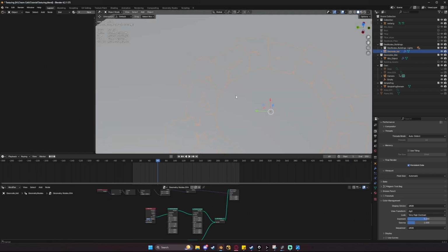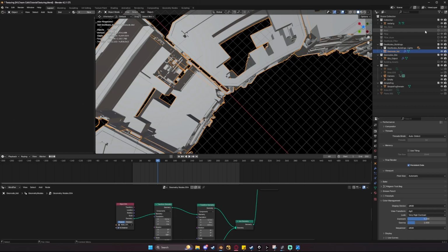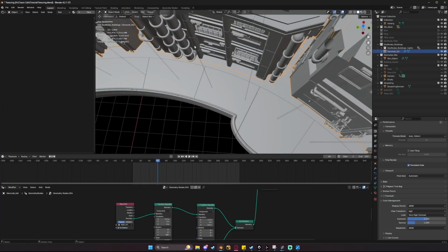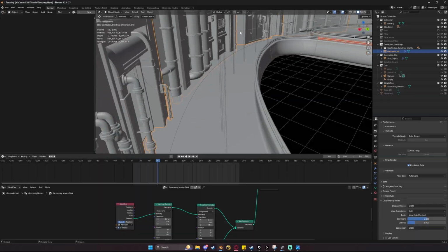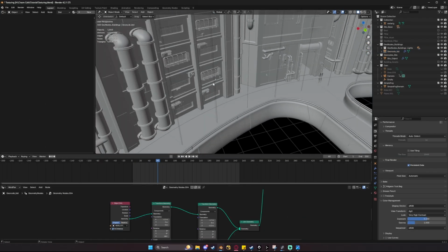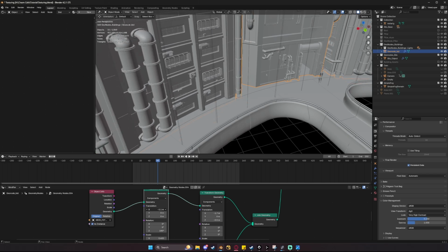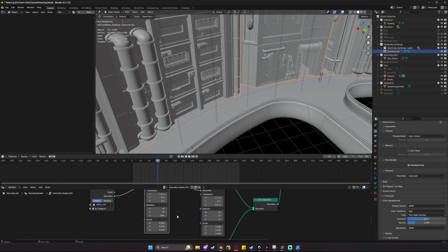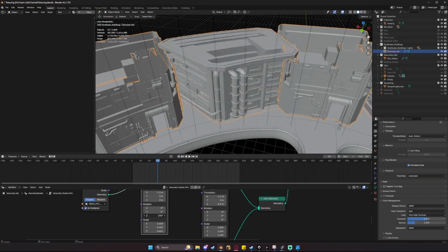One of the things I did was I just repositioned some of these buildings to line up a little bit more accurately here. To get a better view of it, we can enable the silo base collection. And you can see that I've lined these up now to really kind of just be right off the main sidewalk or base layer here. I made this change pretty simply. I added a second transform geometry node, and I just moved some of my buildings until they were in a position I felt right. I think for this building as well, I messed with the rotation.